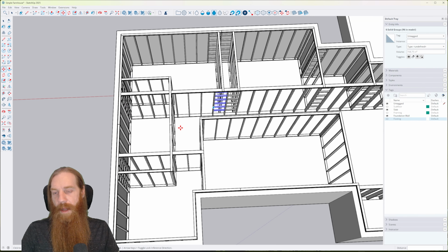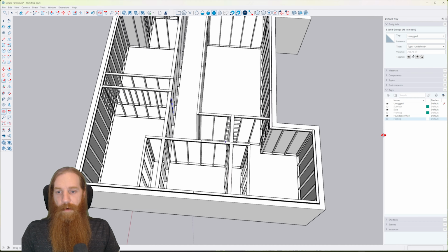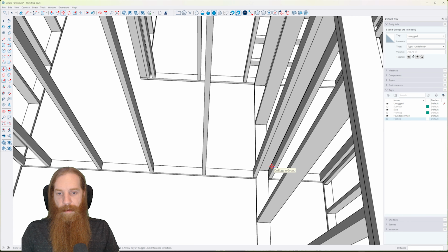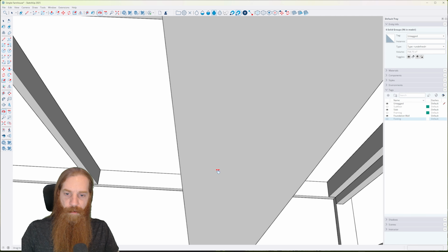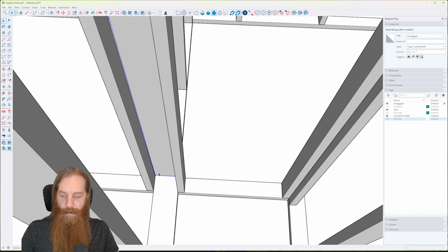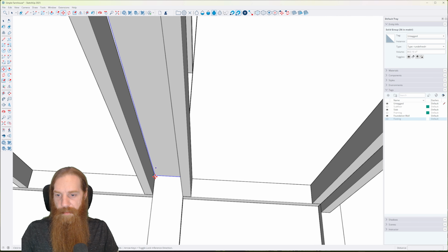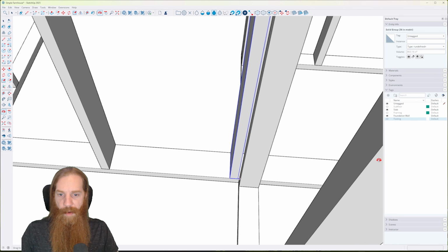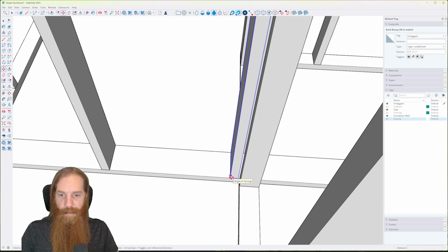Looks like it. Okay. So the only things left are four-way intersections of the walls right in here. There's a couple different ways that we could technically do these. Because they are interior walls, I'm not worried about insulating, although we will put insulation in between these walls for sound dampening, rather. But yeah, we're just going to do kind of a stud pack here to land on.